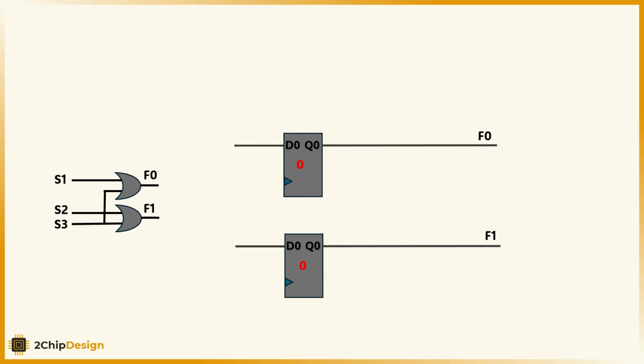Let's break down how we build the system from here. We will use the flip-flops to store the result. Initially, they are set to 0, since there is no winner yet. We will use an OR gate to detect if any flip-flop is set, which tells us that we already have a winner. This creates two states: race ongoing, no winner yet, 0, and race complete, winner has been recorded, where the result of the OR gate will be 1.